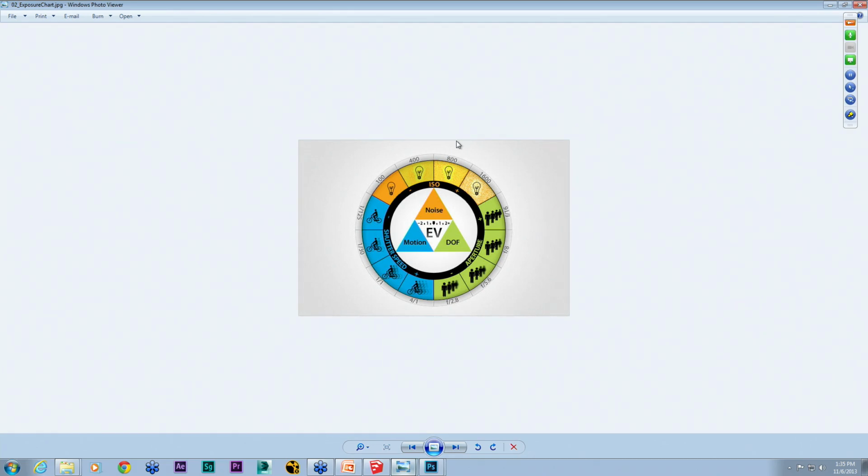So if we approach each of these images through the V-Ray camera with realistic exposure settings and having them work in tandem, then we'll be set, at least from a baseline, to then worry about everything else we're putting into our scene, our materials, the lights, etc. So if we keep the camera at a realistic constant without the downfalls of what an actual camera and film and digital work with, then we get a more repeatable result.